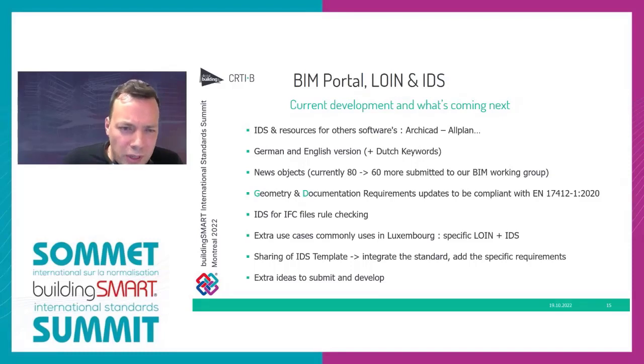We would also like to develop IDS for automatic rule checking. When you generate your IFC, you can check if everything is right in one operation. If you receive an IFC from somebody else, you can check if this IFC is compliant with the level of information need.